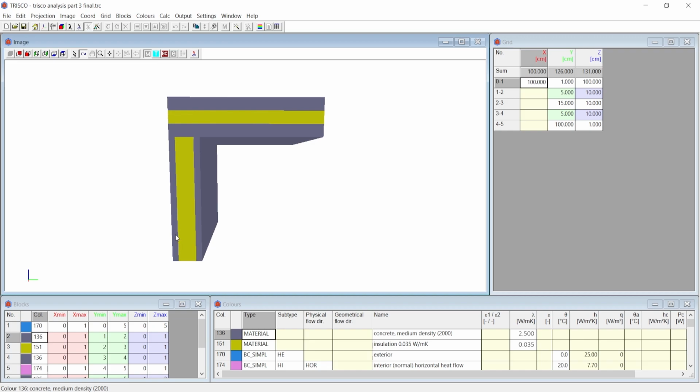The relevant standard for 2D and 3D thermal bridging, EN ISO 10211, does not specify whether interior or exterior flanking element distance should be used. This is specified under national regulation. For example, in Belgium, the outer dimensions are applied. In the Netherlands and UK the inner dimensions are applied. Hence, you must be aware of which of this is to use as per your local standards.